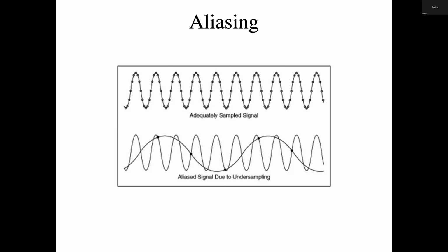It says, well, if I have a curve that looks like this, if I sampled, say, each one of these points on the peak, I sampled at that rate, it would just look like a straight line, right? So I would have missed that function entirely.